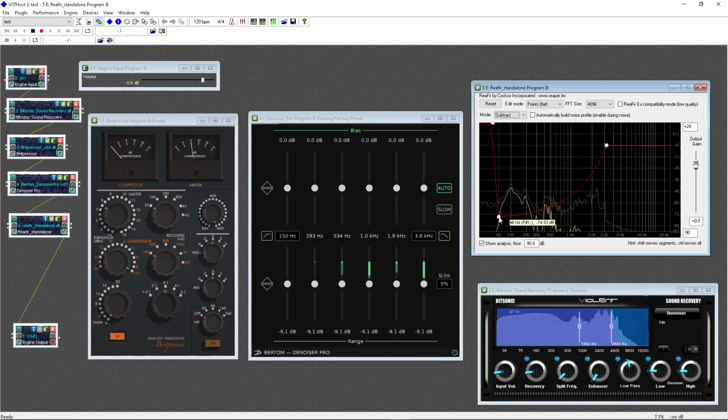Let's place this at around, what's that, 41 hertz? Yeah, for the voodoo guys. Let's take this one. Bring this down. I usually place this about 4 kilohertz, right about here. You're going to have to fuss with this. Left click on the red line, make another point, and bring this straight up. That will gate everything, roll off everything above 4 kilohertz. I like to place a few points in here. Left click, left click, left click, left click. Okay. And let's put a point in around 2.5K right in there.